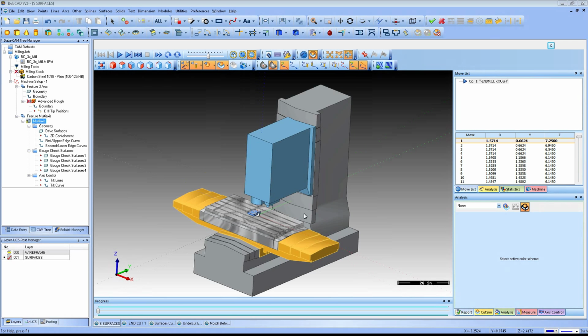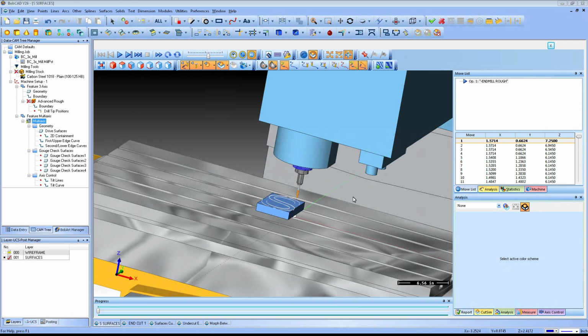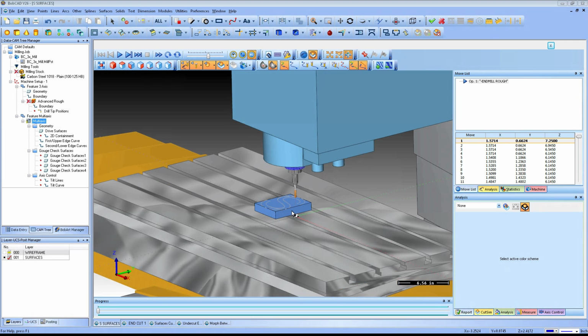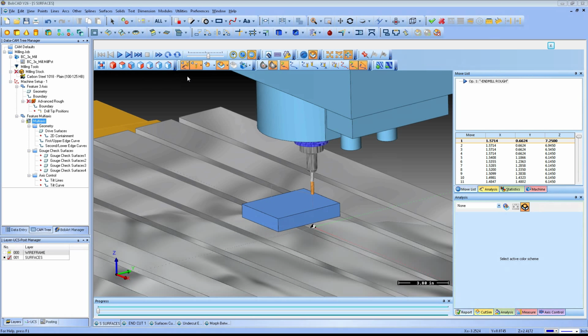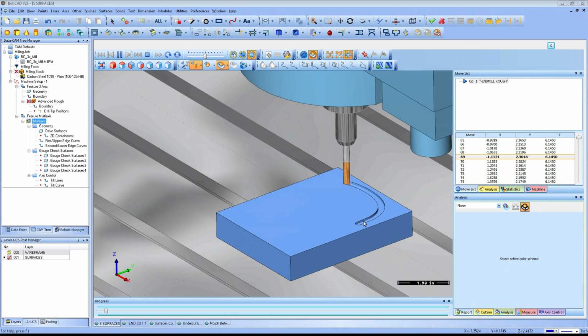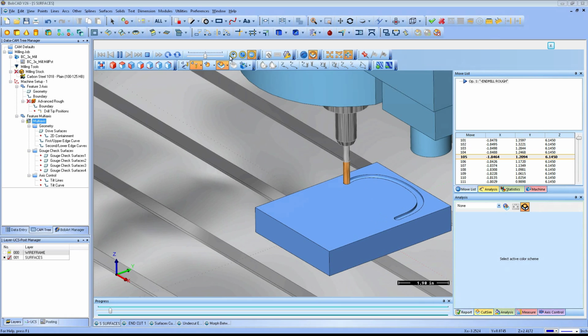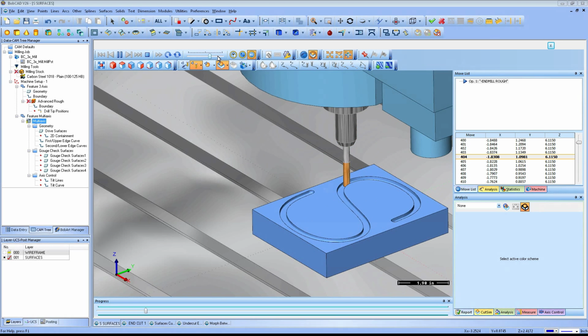You can see with the multi-axis toolpaths as well, it comes with the Pro simulation. So you'll be able to set up your machine, draw your components and set them in there, and actually see the entire machine run in your simulation. Check collisions, fixtures, heads, and things like that. So let's set this here, give it some speed, slow it down a little bit, and hit play. And again, my stock is just a block, so you can see that would be starting off of where the S was. But it's just following that shape, just going back one direction.